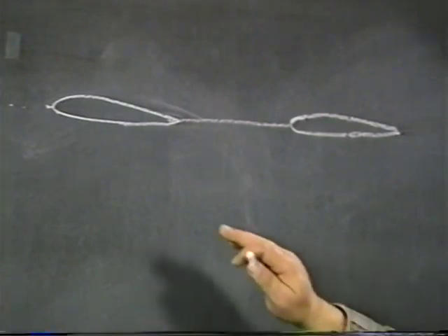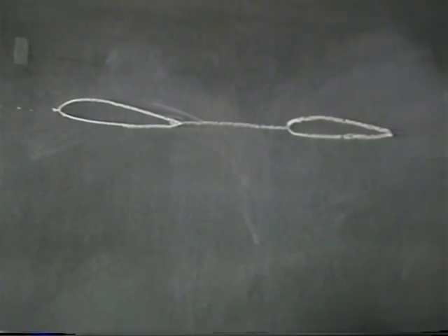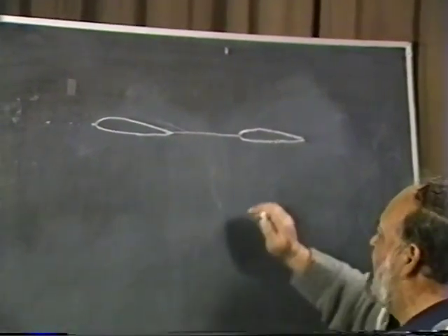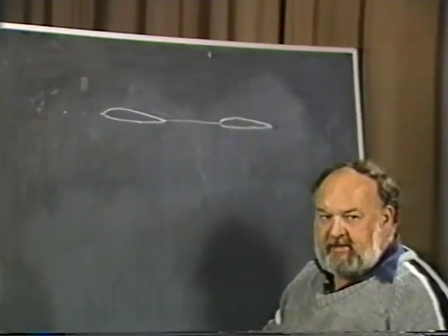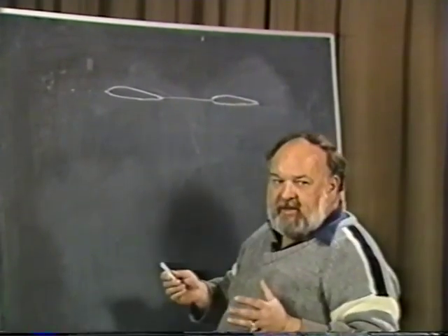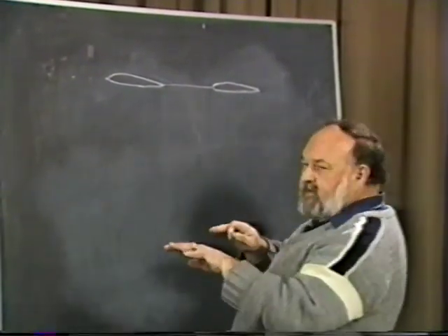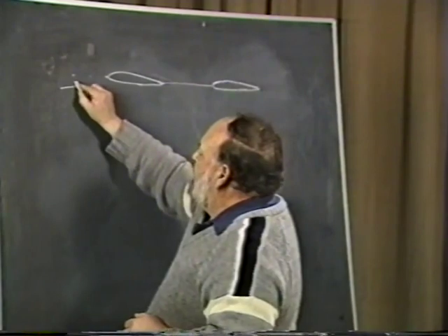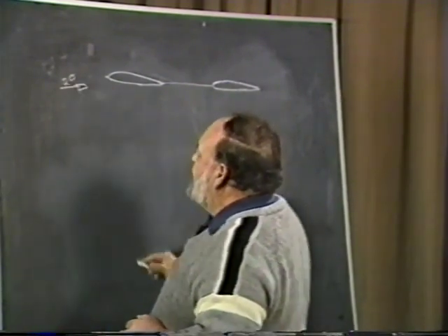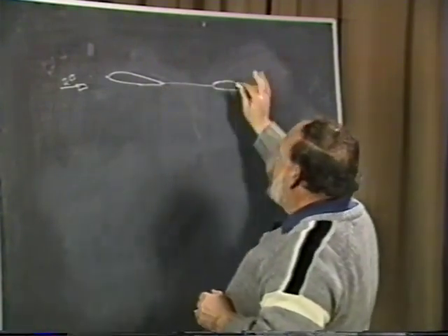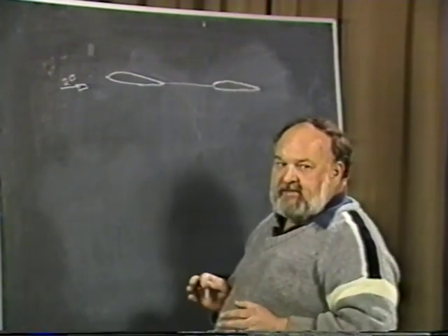Let's take a look at a basic configuration of an airplane having two surfaces, a front surface and a rear surface. Whether this is a conventional aircraft with a large front wing and a small tail in the back, or actually a canard with a small tail up front and a large one in the back, fundamentally everything is identical. But in this particular case, let's start off by saying we have two wings here of the same chord, same wingspan, same aspect ratio, same size, two identical wings, and they're both connected together with a little fuselage at the same angle of attack. If we were flying along at a 2-degree angle of attack right here, and in this case, let's forget the downwash off the front surface on the back one, just to keep everything simple. So we could say the back one, sitting at the same incidence, has the identical angle of attack.